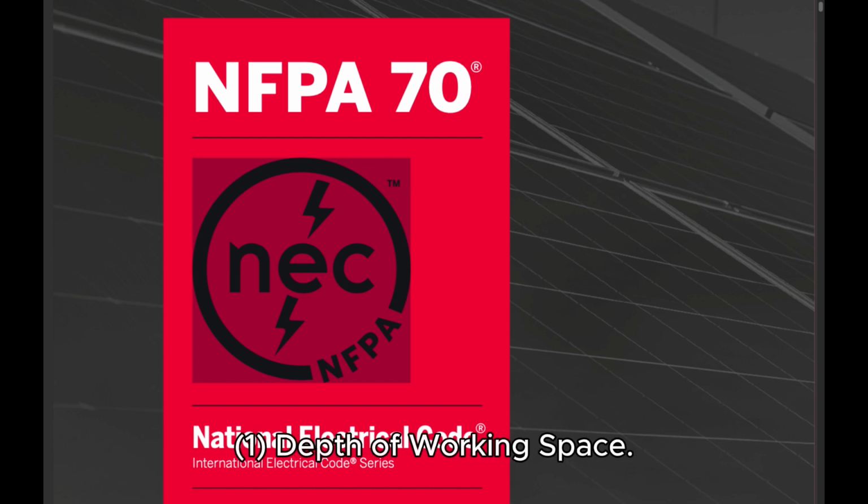1. Depth of working space. The depth of the working space in the direction of live parts shall not be less than that specified in Table 110.26(A)(1), unless the requirements of 110.26(A)(1)(a), (1)(b), or (1)(c) are met. Distances shall be measured from the exposed live parts or from the enclosure or opening if the live parts are enclosed. (a) Dead-front assemblies.